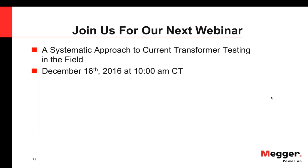In addition, a lot of times when these solar panels are put on, they are put on only one phase. So what they are doing is creating unbalance in the actual network. So we're seeing that as an issue. The unbalance also causes heating effects. And there have been some other complaints as well, such as electronics failing within 15 to 18 months, repeatedly, microwaves failing, things like that.